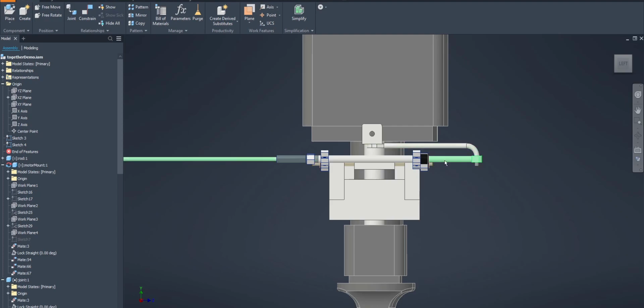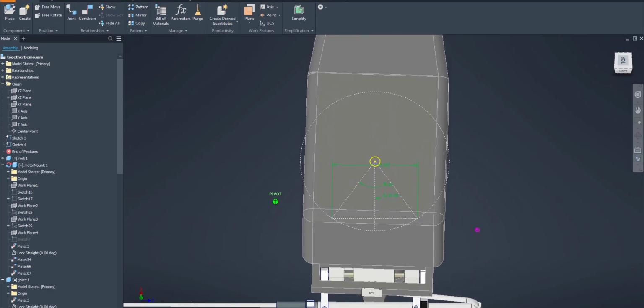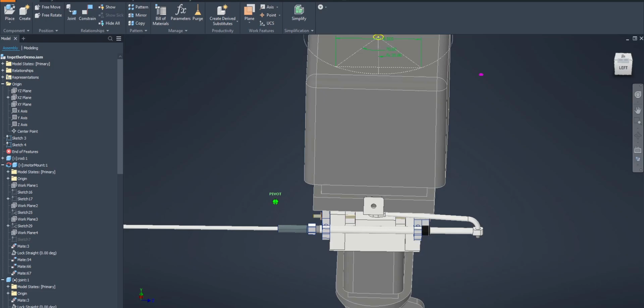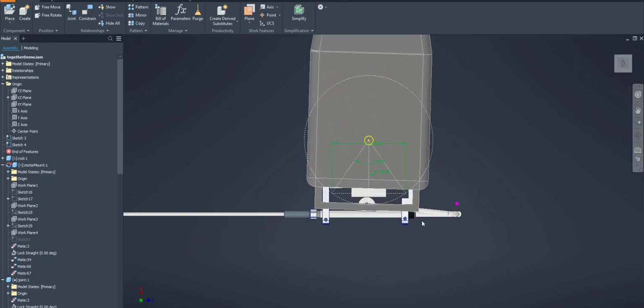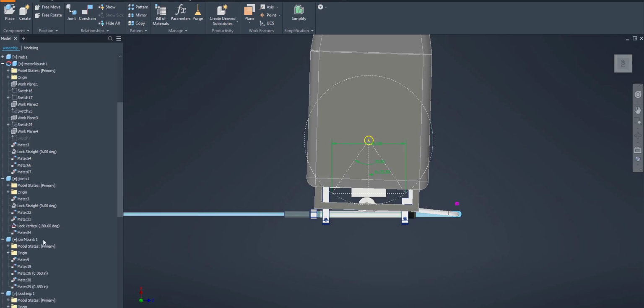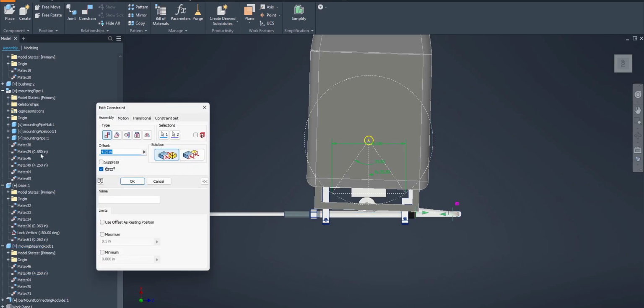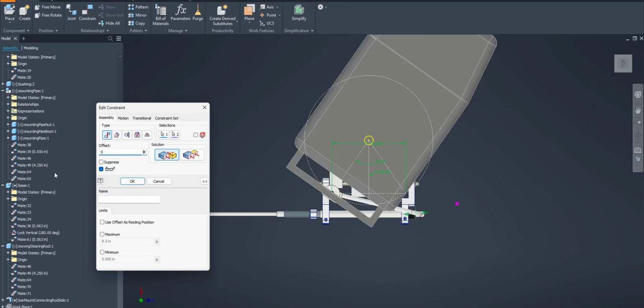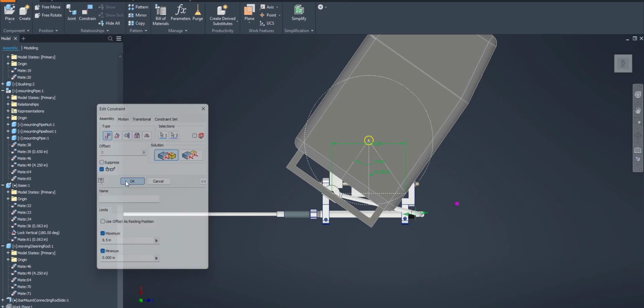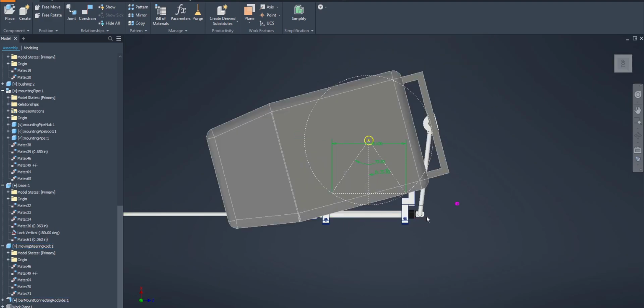This thing is sitting at halfway, so the motor should be straight. And so now what I'm going to do is go back into this part here, and I have it currently locked at the 4 1/4. I'm going to not lock it, and then I'm going to set the maximum to be 8.5 and the minimum to be 0. So that is the distance of the distance.